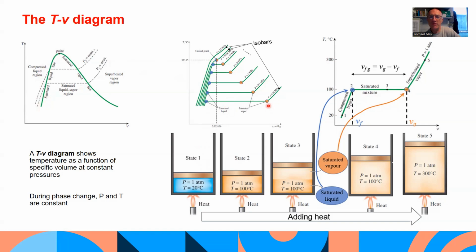Over here, we will have a range of saturated vapor points. If we link them up, we get the saturated vapor line. And where they coincide is called the critical point. Above the critical point, there's no distinction between the liquid and vapor phase. And the liquid, we're dealing with water in this case, takes on new properties of what we call supercritical fluids, which have special applications.